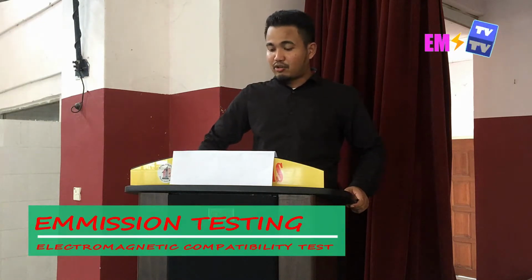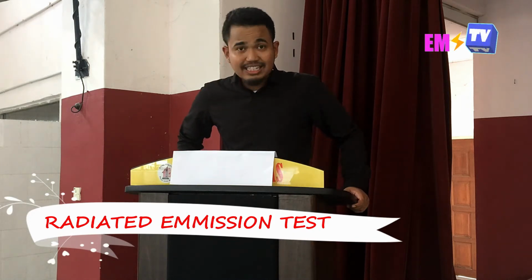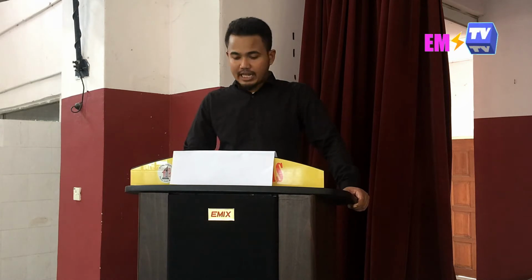So today I would like to talk about the categories of electromagnetic compatibility test. So first of all will be the radiated emission test. It is a concern about how much your product is emitting in terms of radio frequency energy. So it is done in the test chamber, anechoic or semi-anechoic. It is a metal box which stops external signal from getting in the chamber. It also has absorbing material on the wall, so whatever is being emitted from our device is absorbed and does not bounce back and get picked up by the antenna.